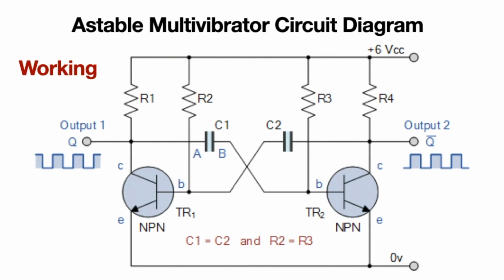output Q bar, here in our circuit we can say that output Q and output Q bar, and we check the output at Q, then we will have the higher value, that will be nearly around plus VCC, and when we check the output at Q bar, that will be around 0 voltage. That means it has a low value, right?